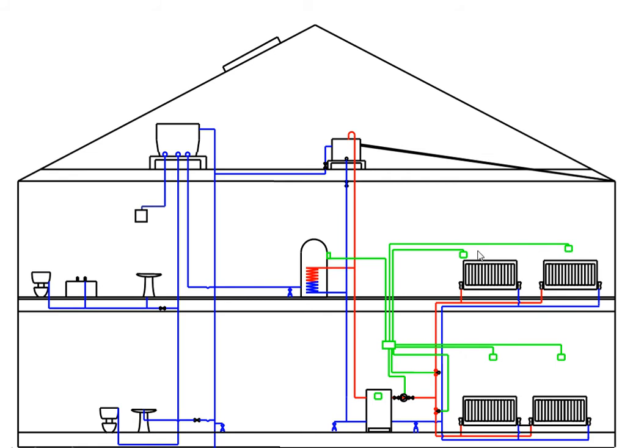So we have our thermostats in the room, they all go back to the control center, with thermostat on our cylinder, that goes back there to the center, and we have another one then on our boiler, that also goes back to the cylinder. So if I want to turn off the heat there, that'll send a signal to throttle down the valve here. It'll throttle down the circulation pump, because obviously you won't need the water circulating as much if you're not heating the whole lot, and you'll turn down the thermostat there in your cylinder also.